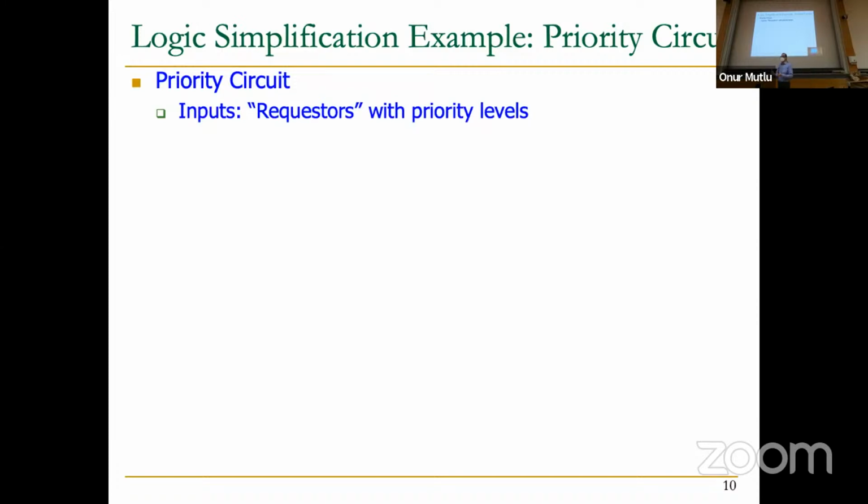Maybe a more interesting example is in a self-driving car. You need to access, for example, a memory location. And there's a single bus to access a memory location. Which important accelerator should get prioritized? Well, maybe the braking system gets the highest priority. Maybe some other vision accelerator gets the second highest priority. Maybe the CPU gets the third priority and the GPU gets the fourth priority. So you can decide a priority level across the requesters.